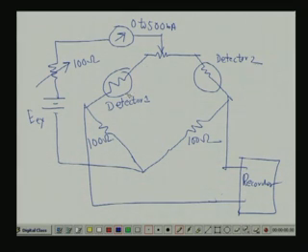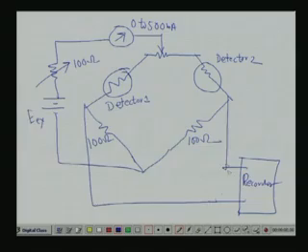So, whenever the elution peak comes, that means when the gas is coming out, I will have elution peaks. So, the detector output will change, because there is a thermal conductivity change there. So, if it changes, I will get an unbalanced voltage that will be recorded in the recorder, right. Now, again you see, in the hydrogen flame ionization detectors, for high sensitivity analysis of organic compounds,